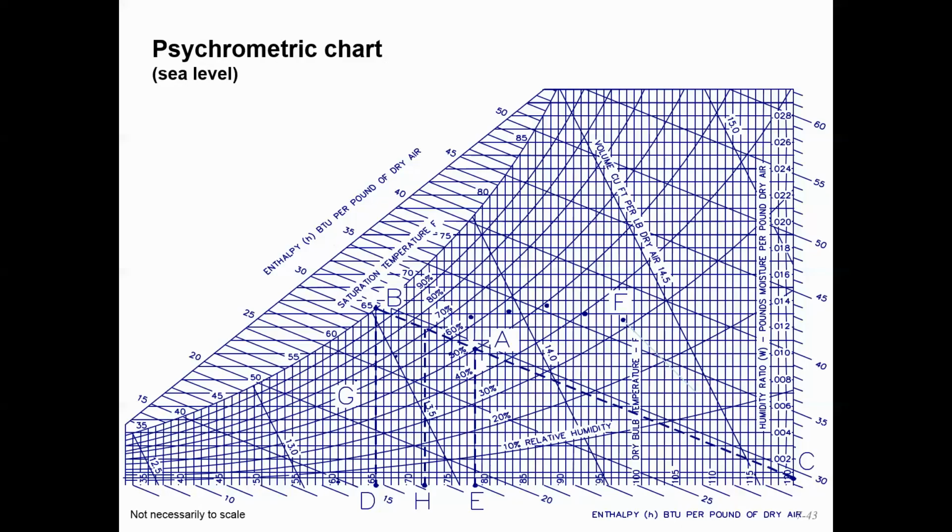Here's what that looks like, a little bit slower. We start with the return air condition that we would expect. In this case, it was assumed that return air would come back at 78 degrees and 50% relative humidity. A constant enthalpy line is drawn up here, and then the next step is to plot as much of that weather data as we can around that state, see where they intersect, and then run a line down. When you read that out, that shows in this case that the economizer high limit set point should be 71 degrees.